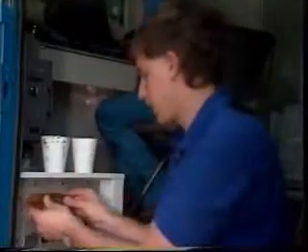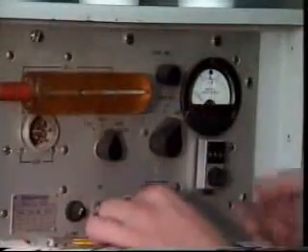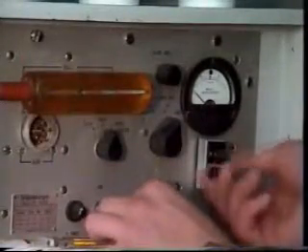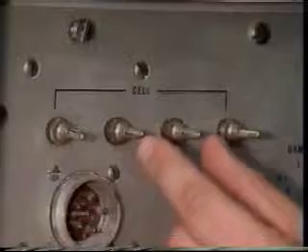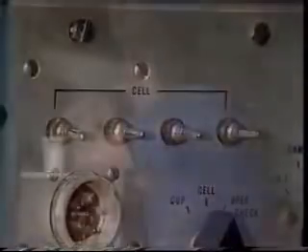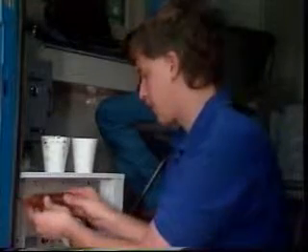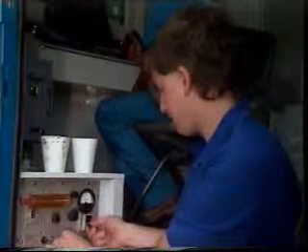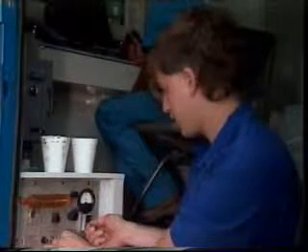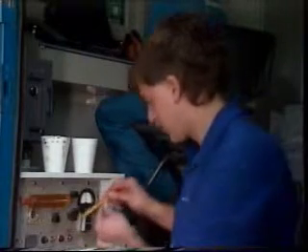We will start with a simple resistivity measurement to illustrate the basic principle, and we will then be able to apply this understanding to all the other resistivity tools. In the determination of mud filtrate resistivity, a very simplified and fundamentally understandable method is used. These two end electrodes are the current electrodes, while the two center electrodes are voltage measurement electrodes. When the sample of mud filtrate is introduced and a constant current is passed through the sample from one current electrode to the other, a voltage drop is measured at the measurement electrodes. With two simple equations, we can easily understand the process.